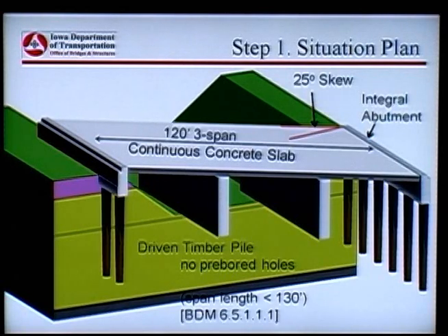Based on the bridge design manual, if the span length is less than 130 feet, we do not require any pre-bored holes. Right? And an elevation of 922.